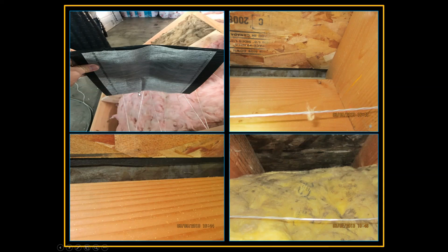You're probably going to ruin your warranty by doing that. My suggestion is buy a ridge vent that doesn't have leaves and meshes that they can use, and more open than this. You can't see it in these photos, but there really isn't. You should have 2 inches from the ridge down on both sides, and both of these are about 1 inch. So it's 2 inches, but it should be 4 because it's 2 down from each side.